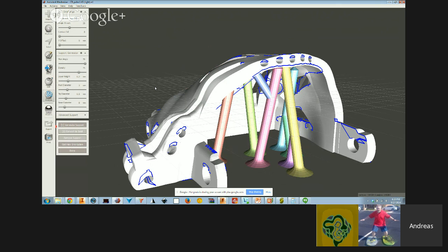You have to make sure you change the size back to a ratio before you export it? It should not. STLs are unitless. So depending on where you're coming from, for example, Maya is centimeters. So if it writes out an STL, it's going to be in centimeters, but Meshmixer will read it as millimeters. So in that case, you might need to scale it by 10. It's just dependent on wherever you're coming from.